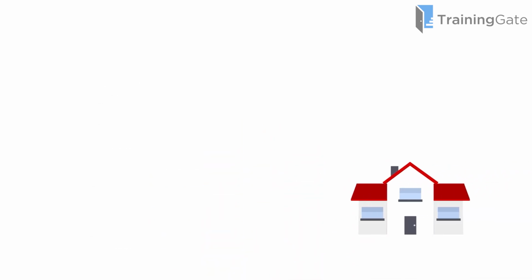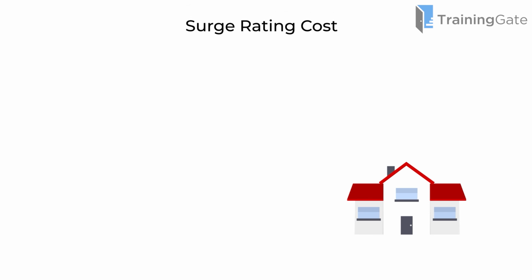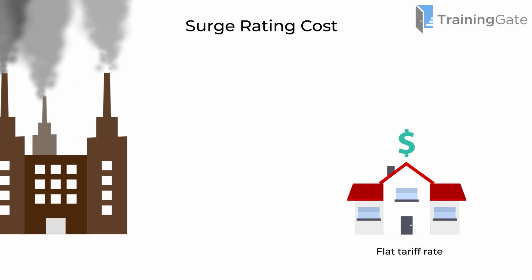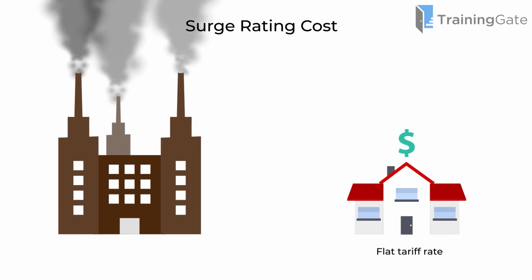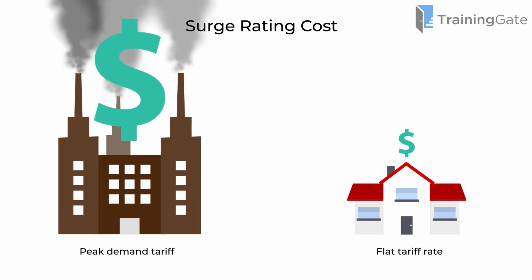It's important to note that the surge rating cost per kilowatt hour on most domestic sites is insignificant when considering a flat tariff rate, whereas on a commercial or industrial site, this peak could be costly, and the battery system may need to operate to reduce this.